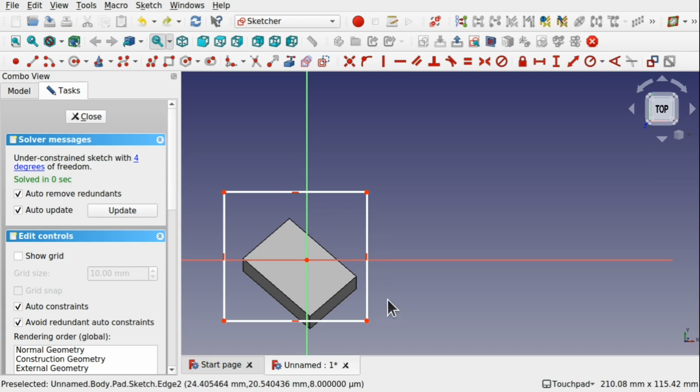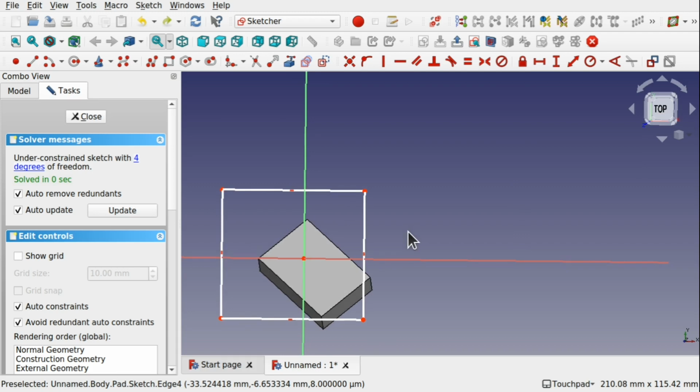So you need 4 sides for these to connect. They won't merge 2 sides in together to create a blend between those. You would have to do that yourself with the tools in the Curves Workbench and in the part design. You can do that with the join curve, split curves to shape your shape to have the right number of faces on there. And we'll show you that, how to do that.